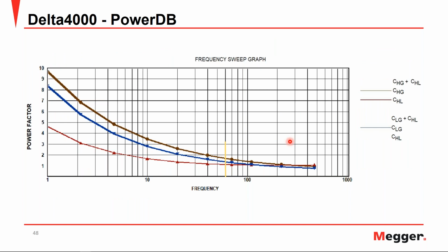If we scroll down from there, we can see a window like this that shows the actual narrowband dielectric frequency responses being highlighted and shown graphically. And you can see again from 500 to our 1 Hertz, we have our 60 Hertz value here. And then as the sensitivity towards the lower frequencies increases, we have our higher power factor at our 1 Hertz measurement.